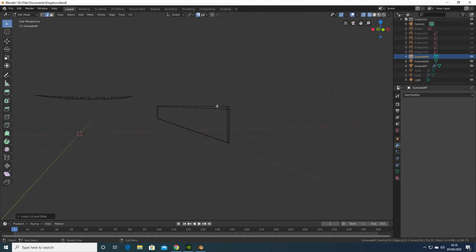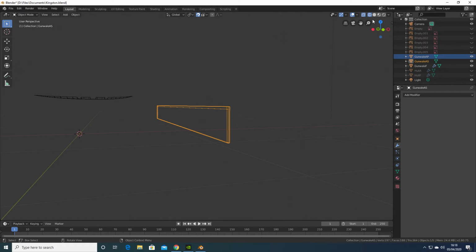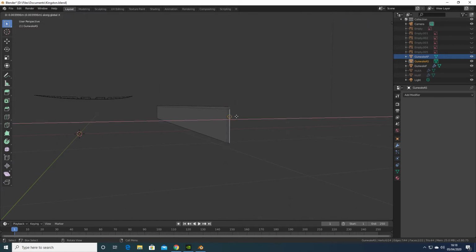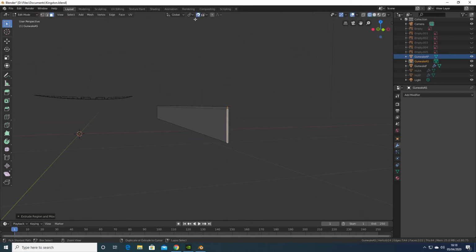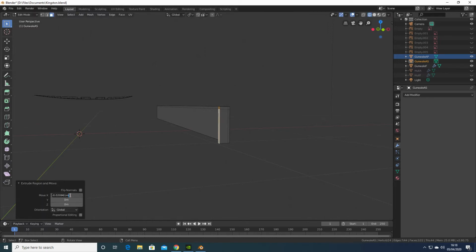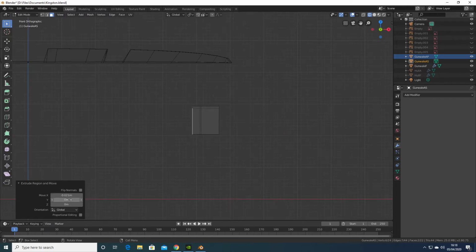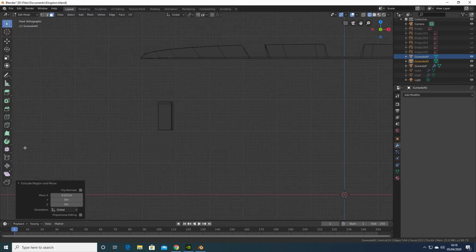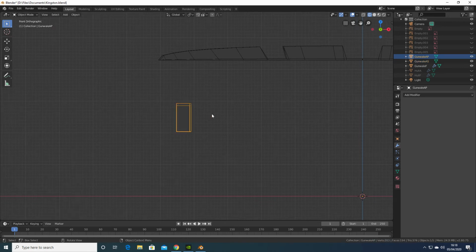And now we'll just zoom in slightly, highlight this object, make sure we're in edit mode, and we'll select the face. We'll select these two faces and we'll extrude in the x-axis. Actually we need to take off snapping. Now let's E X and bring this in a little bit, just visually. And we'll copy that amount. And now we'll go over to the other side.